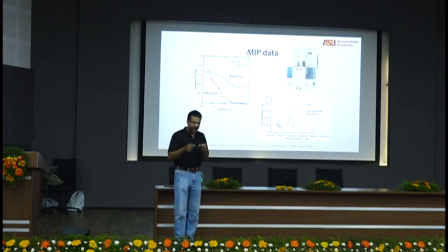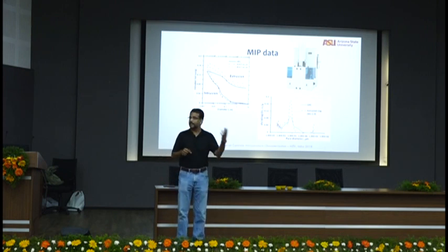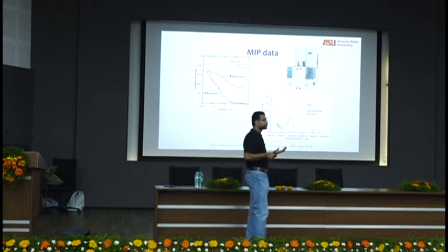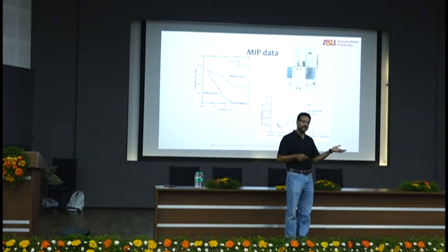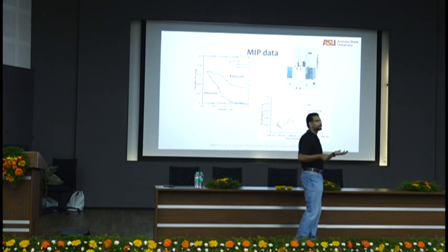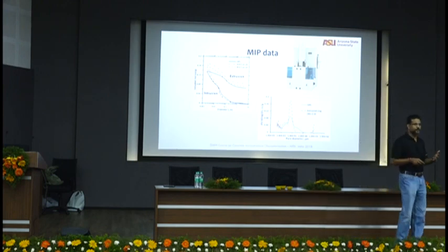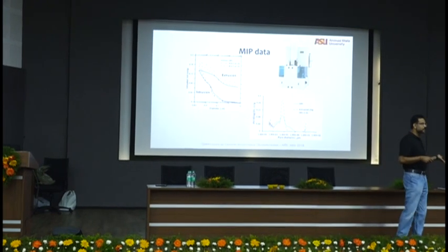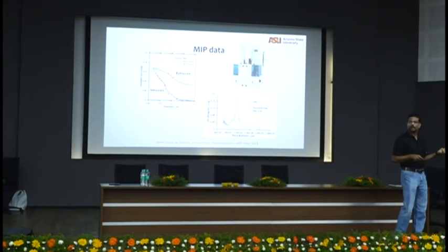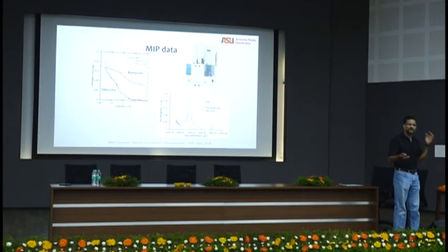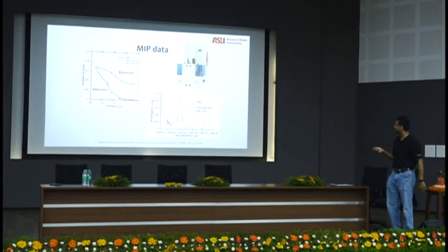So if I want to enter a really small pore, I need a higher pressure, right? And then pressure is proportional to the contact angle. Pressure is proportional to the surface tension. Pressure is inversely proportional to the radius. P is equal to 2 sigma cos theta over r, or 4 sigma cos theta over d. Simple, very simple, straightforward.